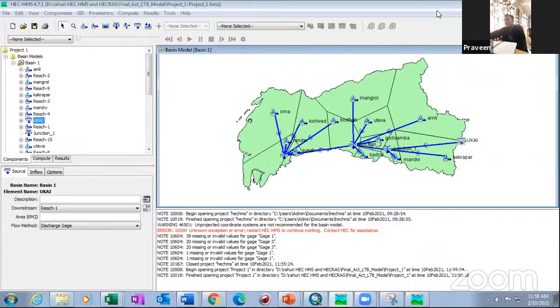What if the land use and channel properties change over time, say 20 years? Does HEC-HMS have a provision for this as well? No, actually, in that case we have to have a dynamic way of doing the models. This question is really good, because in a 20 or 30 year simulation, sometimes even your whole basin catchment features will change, right?